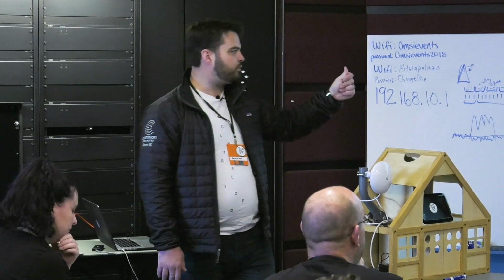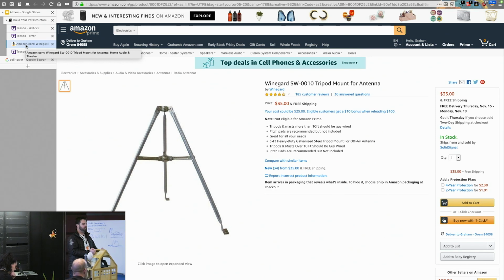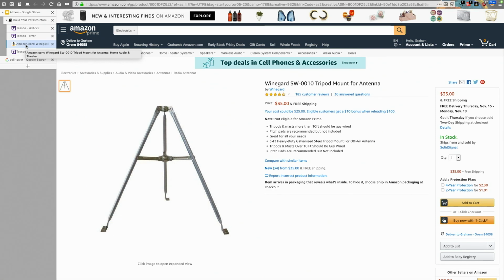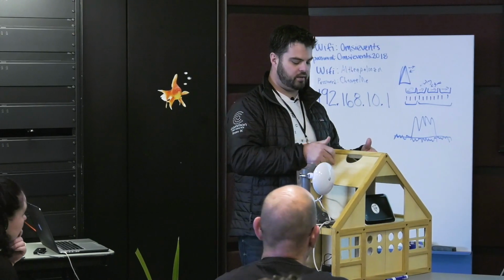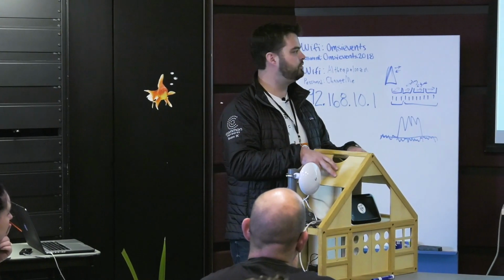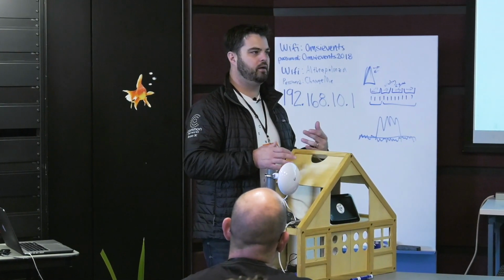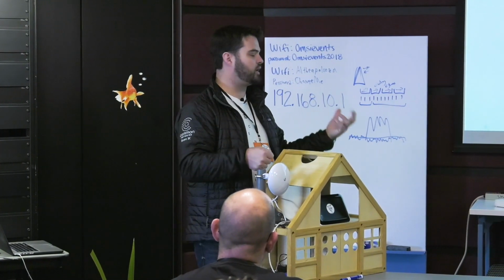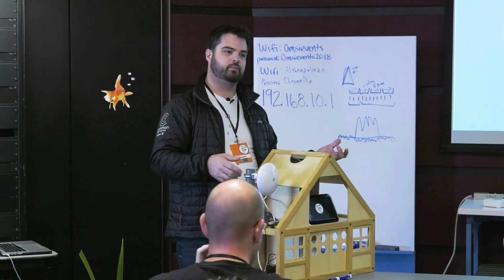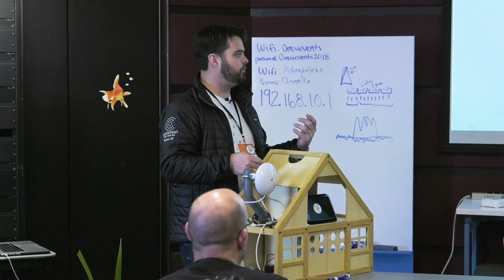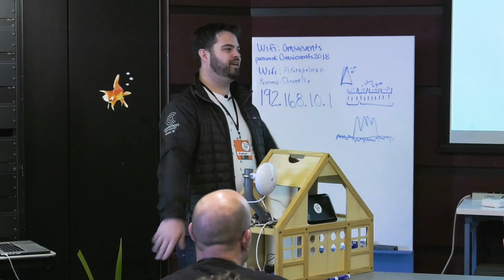This is just called a tripod mount. This is great for mounting over the peak of rooftops. Mount this over the peak and drill it into the roof. The downside of something like this is that it does require penetrating the roof. So it needs to be sealed really well so that you're not causing any leaks. But they are very sturdy once they're in place, and means that you don't have to haul 300 pounds of cinder blocks up on the roof, which is great.